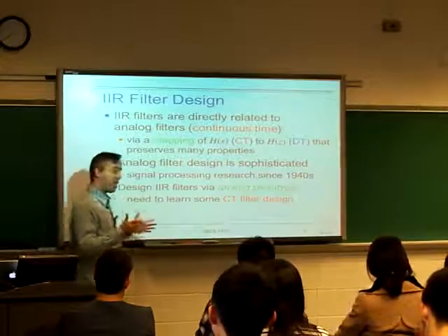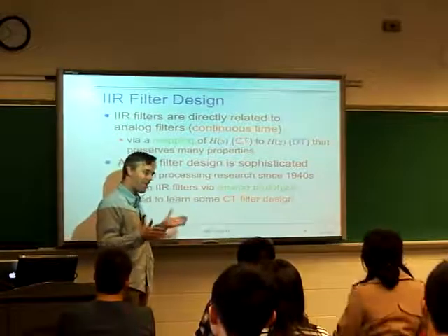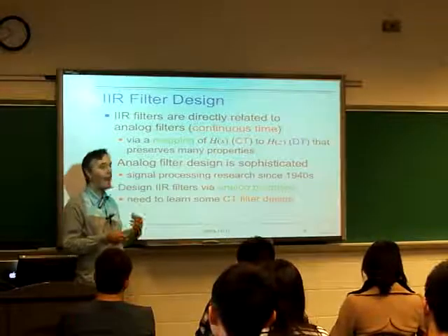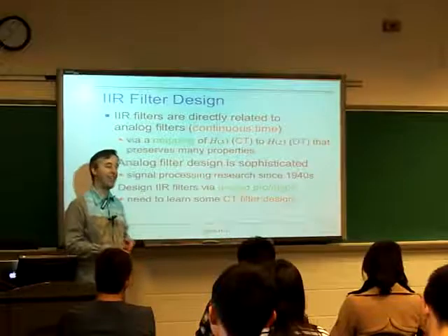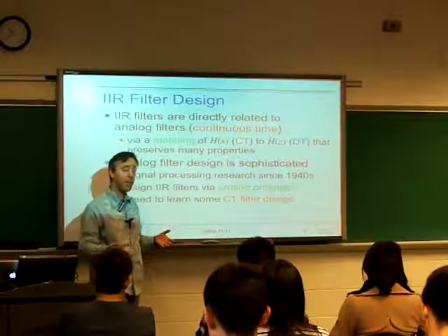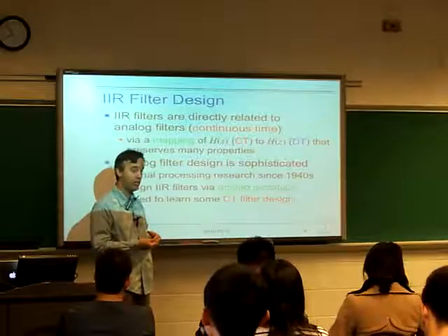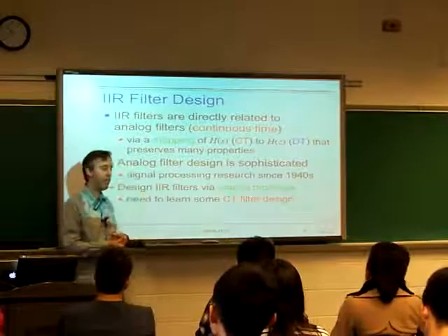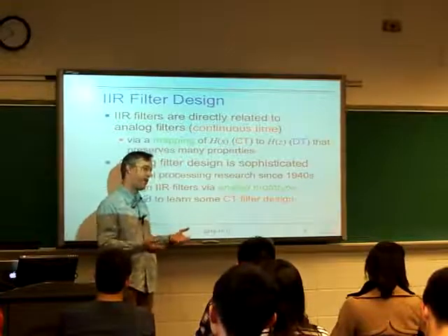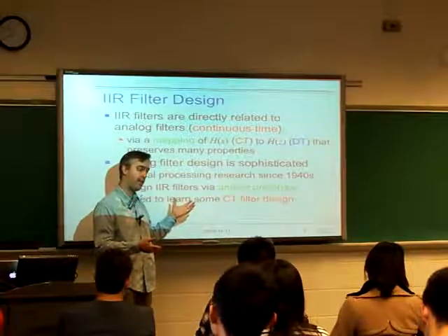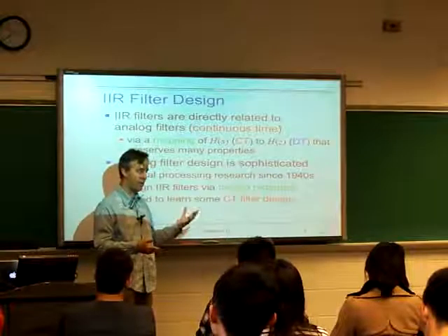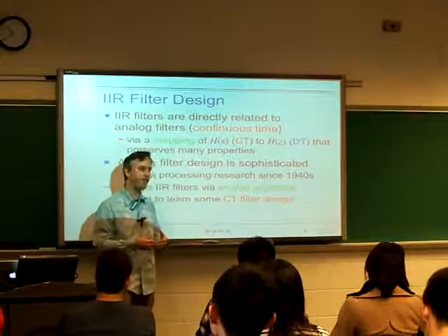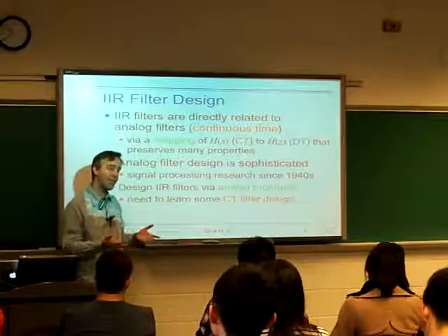So now we've seen the choices. As technology advances, the way it typically happens is computational cost becomes less and less of an issue. The processors become, whatever it is, 10 times faster every 3 or 4 years. So the question is, well, we had to use IIR filters in the past, but now we've got the computational power to use FIR filters, so why would we even do IIR? That's an interesting, that's a valid point.